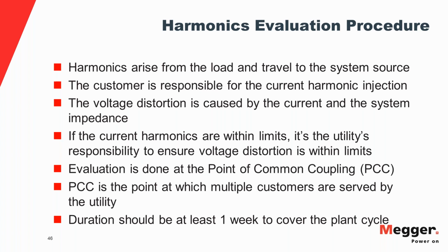Evaluation is carried out at the point of common coupling. Point of common coupling is a point at which a utility serves multiple customers. And as I said, the duration should be at least 1 week to make sure that the plant cycle is covered.